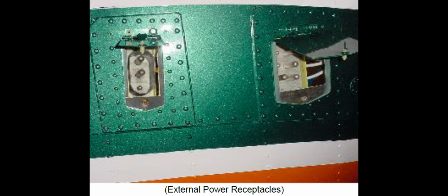DC external power receptacle. The DC power receptacle is located on the right side of the helicopter, forward of the electronics compartment door. The receptacle permits DC power from an auxiliary power unit to be applied to the helicopter electrical system during ground operations. The 3-pin receptacle contains a common ground pin, a high current pin, and an additional low current pin to provide DC control voltages for relay excitation and lighting of the caution advisory panel, external power connected light.